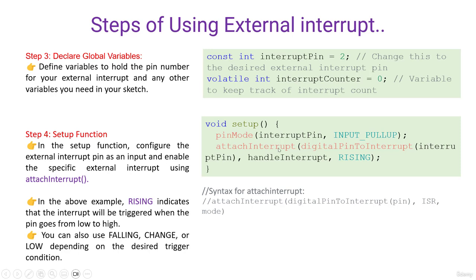So this is the attachInterrupt syntax. After writing that, digitalPinToInterrupt, you need to define the pin number here. Then ISR, you need to put your interrupt service routine function name here. Then comes the mode.